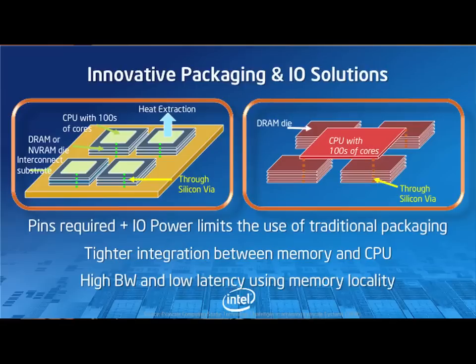And that's what I meant earlier when I was saying for exascale systems we need the system node concept to be as simple as possible and as scalable as possible. And if we're putting multiples of those inside of a multi-chip package, we're eliminating a lot of PCB connections, a lot of error transmissions between the memory and the processor that go from DRAM through a PCB and ball grid arrays and so forth.